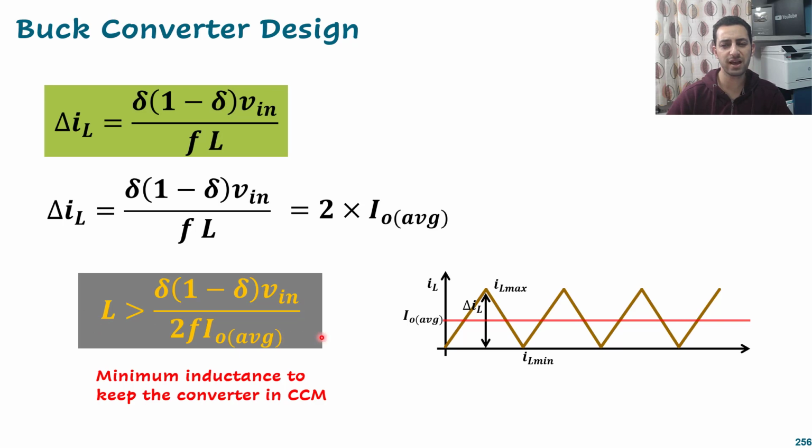So what is the disadvantage of continuous conduction mode? It seems that we should always consume current. It doesn't work in continuous conduction mode if we have no load, because the output current will be 0, and that means we can't actually maintain that equation.